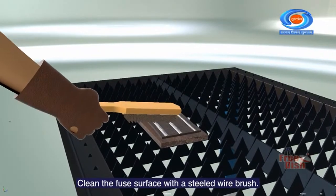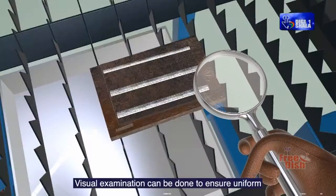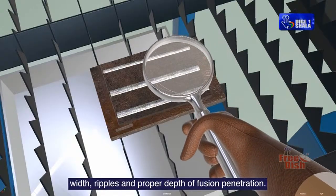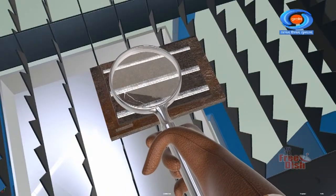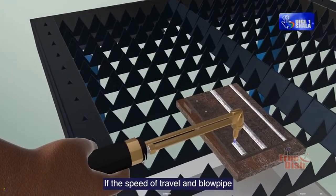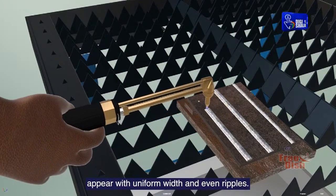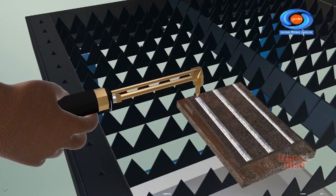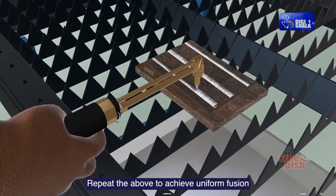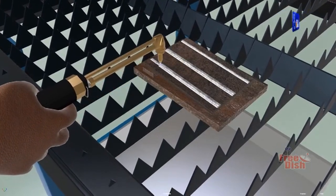Clean the fused surface with a steel wire brush. Visual examination can be done to ensure uniform width, ripples and proper depth of fusion penetration. If the speed of travel and blowpipe motion are correct, the fusion runs will appear with uniform width and even ripples. Repeat the above to achieve uniform fusion and better manipulation of the blowpipe.